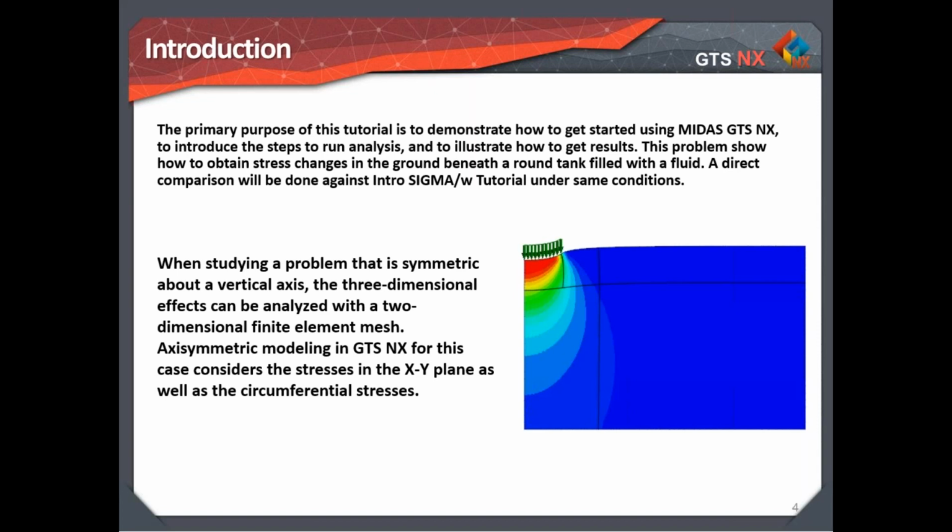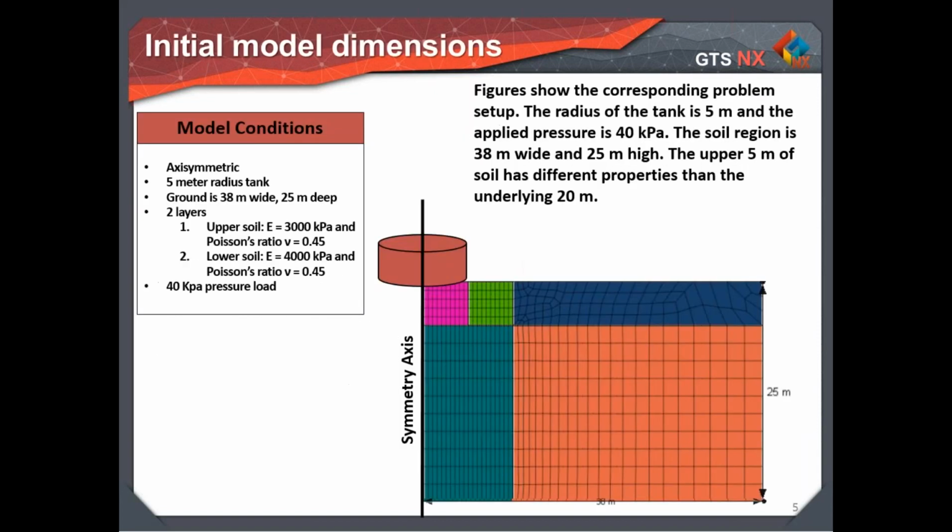be considered a tank. In this case, what we're looking at is considered a symmetric model, and so we can model this almost as a 2D, but in reality it's called an axisymmetric file. What that means is that if your model, in this case a round tank, is completely symmetric, you can actually just simplify it. You can take an axis of symmetry and just take almost like a slice, and the program can then give you results as if you were looking at the whole model.